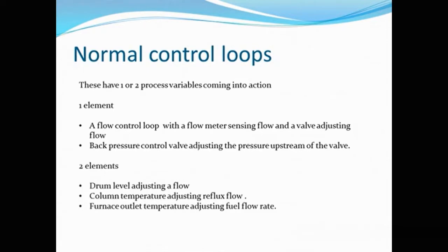The example is, if you are adjusting a flow through a pipeline, you are measuring the flow through the pipeline and adjusting a valve in the pipeline itself. So you are measuring the flow, controlling the flow. It's only one element coming into play. The other situation is when two elements come into play, like you are controlling the level of a vessel by adjusting a flow from that vessel, or adjusting the coolant temperature by adjusting the reflux, etc.